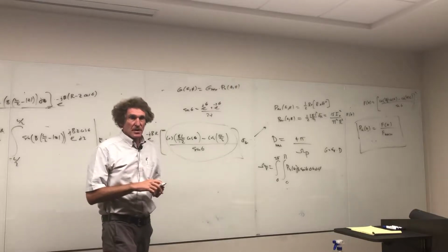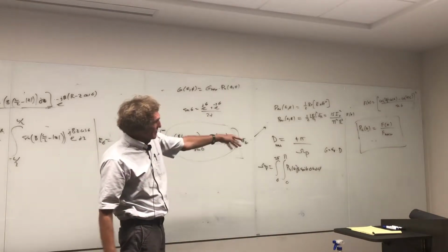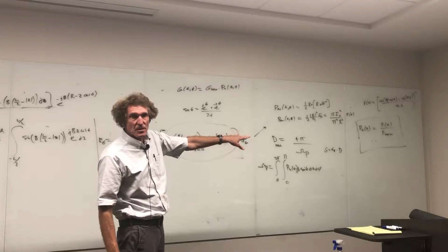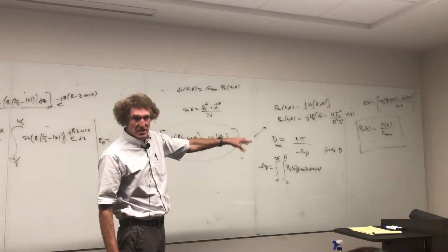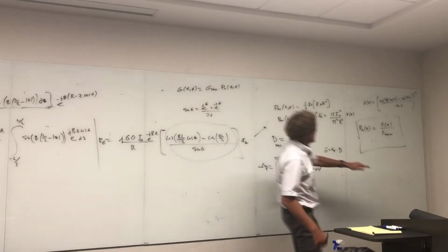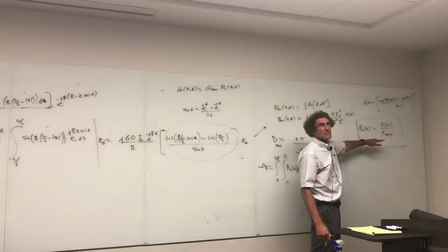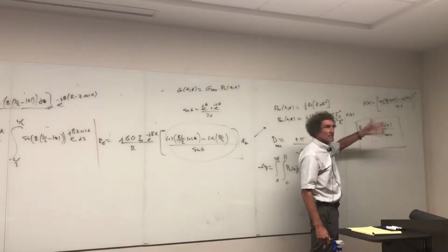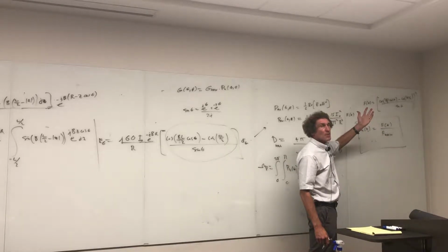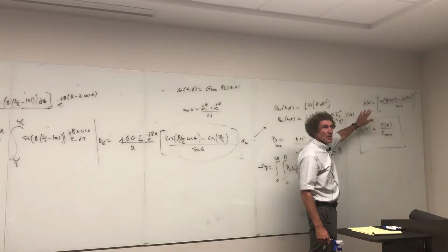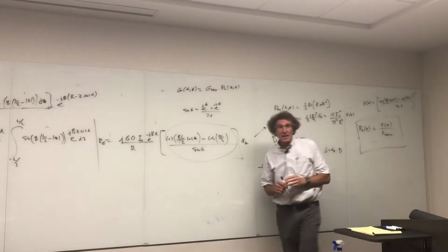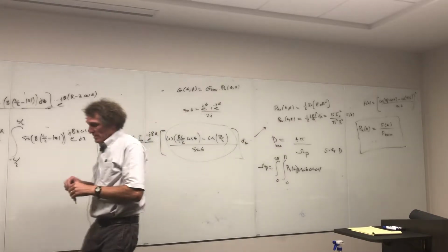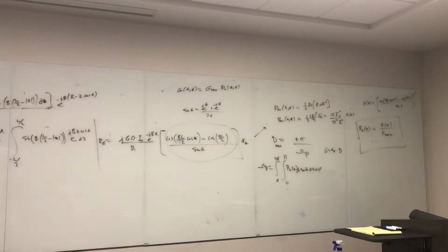I'm going to tell you one other thing: a lot of the stuff I'm saying here, I'm kind of underscoring, even though it seems simple and obvious, are things that I know people make mistakes on. Guaranteed. I see it every semester. I teach this course, and it's usually one of these things: somebody's half there in class, and they don't bother going through with care what this could mean. Because that thing, if you take it for a full wave dipole of full length, you're going to get a maximum value of about 4.5 to 5 for that angular function. Actually, it's squaring that, I think.